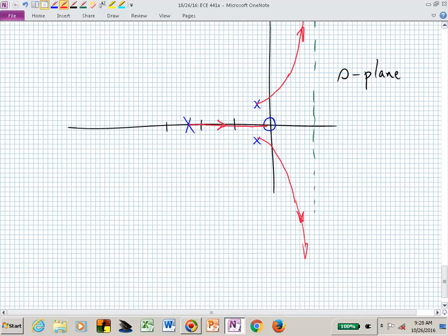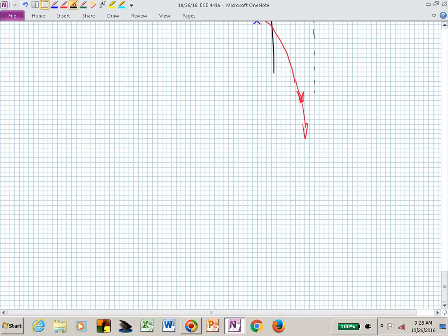And what does this tell you about K? Is there a limit on K that you can adjust that knob before you become unstable? Yes, there is a K beyond which you're going to be in the right half plane, and you probably don't want to adjust your gain K any larger than that. Now, what's another possible pattern? But it all depends on the relative spacings of these poles and zeros. Let me just quickly...